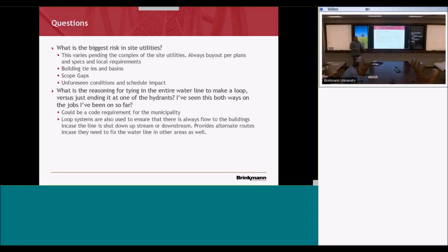Any other questions on site utilities? Yeah, I got one on the as-built plan. Is that something that our sub would go down and take flow elevations, for instance, with a total station before they backfill, or how is that actually done in the field? Marking out the elevations of the pipe, and so on. Well, I buy it out with my surveyor. Sometimes the civil engineer already has it included in their scope to the owner. But ultimately, they just go back after it's all done. They pull the lids, pull the caps, and stick their grade rod down there and get their information.